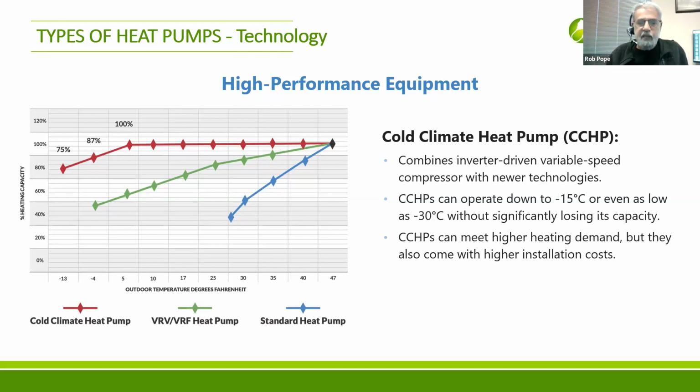A blue line, that blue line represents a standard heat pump, single or two stage. It starts at 47, 48 degrees Fahrenheit. That's the starting point. That's the gate from which all heat pumps start. That's the nominal capacity. So you can have 3 different types of heat pumps, like in this case here, all say 4-ton heat pumps. There are 4 tons at 48 degrees Fahrenheit.